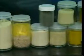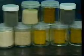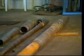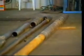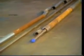The high quality of gravel pack material is essential, and quality control must be employed. Specifications of gravel pack sand have been outlined in API Recommended Practices number 58. The most common and effective method of gravel placement utilizes a piece of equipment having a setting tool crossover assembly and a lower extension assembly that includes a screen.